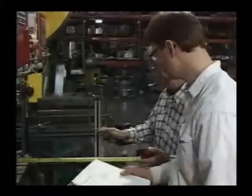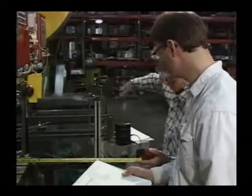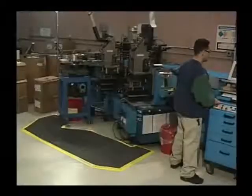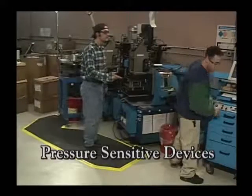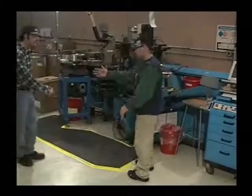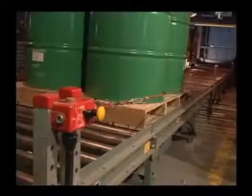If the machine is not stopping quickly enough, adjustments to the light curtains or the machine's braking mechanism can usually fix the problem. Like light curtains, pressure-sensitive devices are also used to protect workers by stopping machinery movements. There are two types of pressure-sensitive devices, trips and mats. Both types can be positioned around the machines to keep workers from entering hazardous areas.